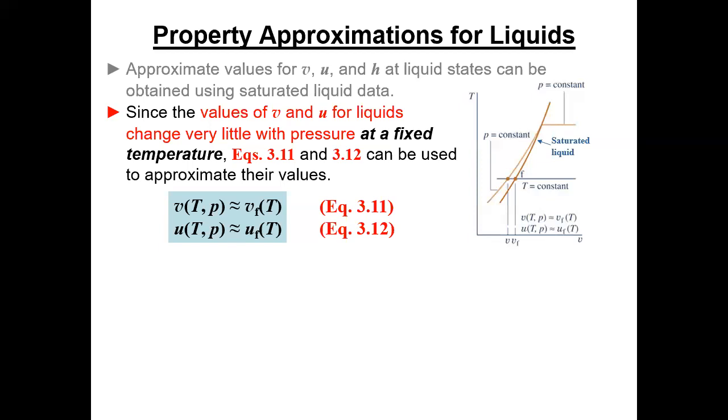I said, okay, so I'm going to keep that temp because I have to keep the temperature the same. I said, okay, well, let me make the pressure 300. Just pick a number. That's like 233 psi away. And the internal energy changes by 0.12%. So for many, many analyses, you don't know the numbers that you're putting in with that degree of accuracy. So what difference does it make if the internal energy is off by that amount? And in a lot of cases, it doesn't.